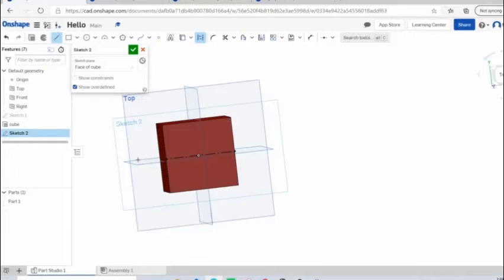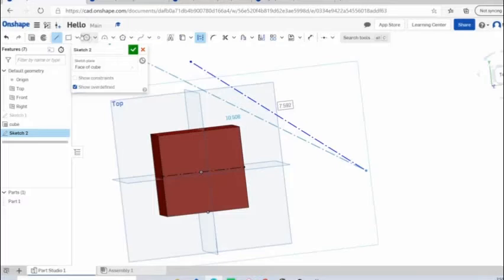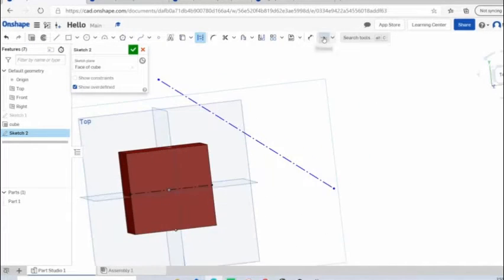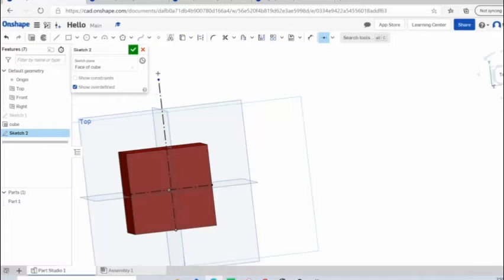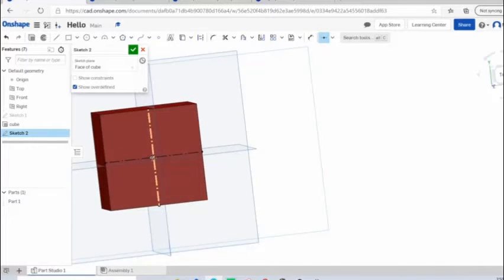Here you go. We're going to make another construction line, and this is going to run through the middle of this. So again, actually we're not going to put the midpoint in yet. We're just going to draw the line. Again, I'm going to draw it way out in space, so you don't just click on here someplace that looks right. You'll actually use the midpoint function. So click on the little endpoint of this line. Click anywhere on this line, from the end of here, anywhere on here. There you go. See, it has a little cross. All right.